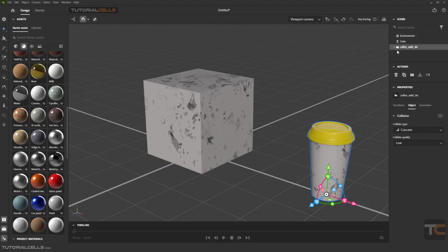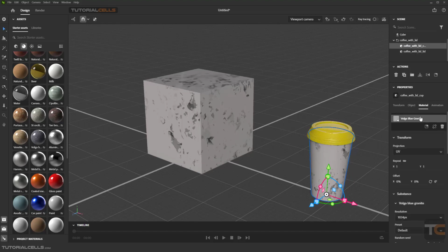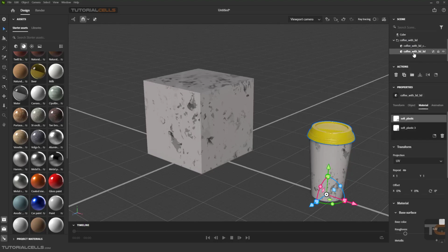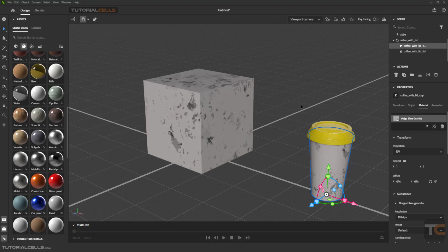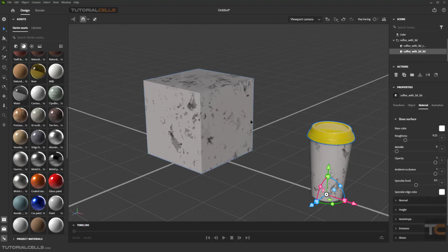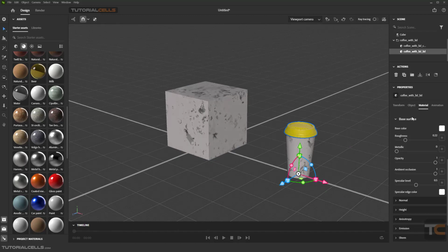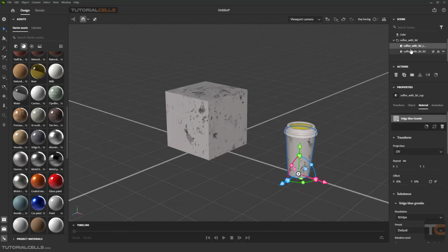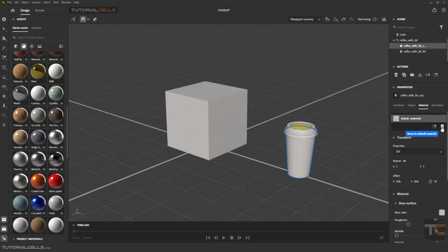You can go to the selection. As you can see in here, if you open it, we have two parts, and each part has a different material. If you select the group, we don't have any material tab. We have two parts, main body and lead. For example, for lead, we have these materials, soft, and for this, and then you can access the material of that and change its properties there. Or, for example, for main body, you can come here and delete the materials. For lead, delete materials. As you can see, you can unlink the materials of that.